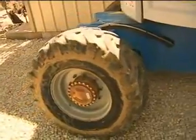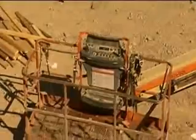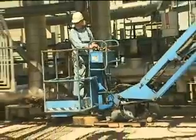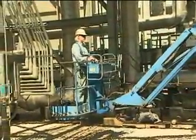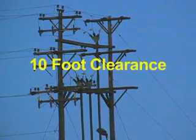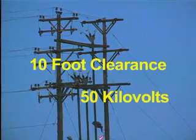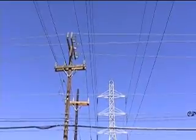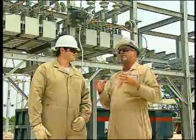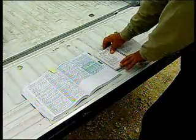Hazards that may create dangerous driving conditions, such as overhead power lines, holes, drop-offs, bumps, lumber, tools and debris must be identified and procedures to avoid any hazards made known to all employees. OSHA requires personnel to maintain at least a 10-foot clearance of all power lines with less than 50 kilovolts. If a power line has more than 50 kilovolts, additional distance is required. Employees should consult with their supervisor to determine the proper distance needed. Electricians have different guidelines and should consult with their employers concerning this issue.